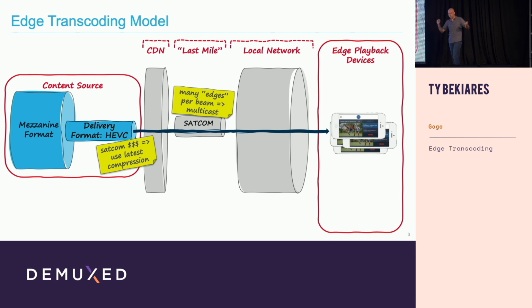There were some things that were the same. It may not be inherently obvious, but even your IP SATCOM links support a multicast or broadcast model. So if you have a number of planes in a given beam, generally it makes sense to multicast. There's a whole discussion that we could have around that. It's pretty interesting. There's times, if you only have one or two aircraft in a beam, that it would actually be more efficient to unicast. Because as soon as you start multicasting something, you don't have any ARQ, you have to operate at a lowest common denominator modulation encoding, et cetera, et cetera.